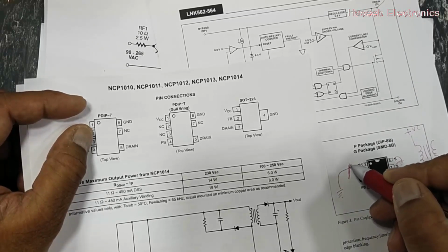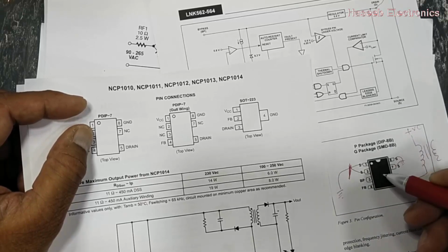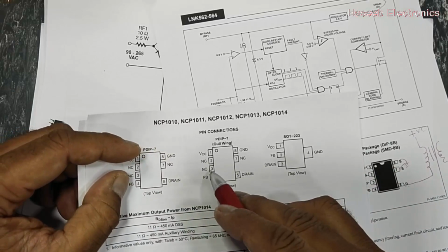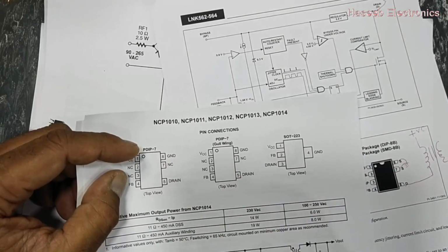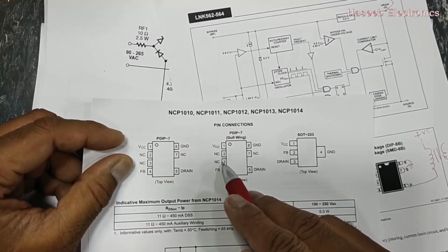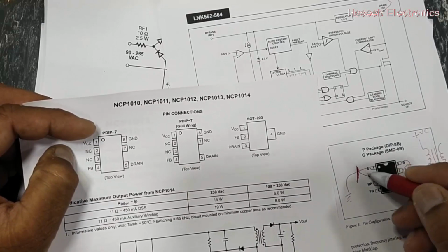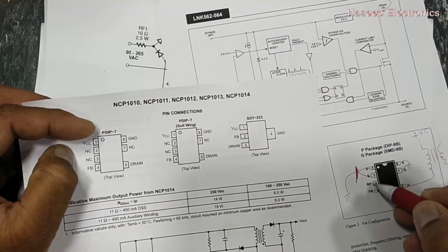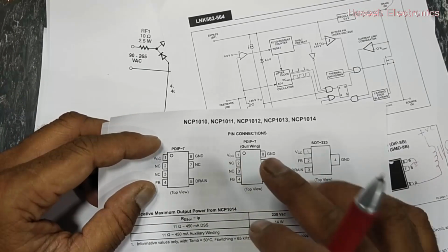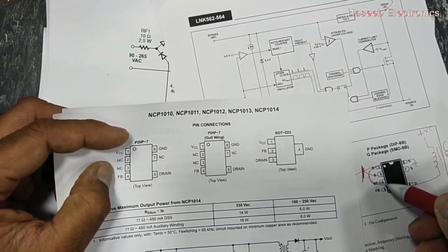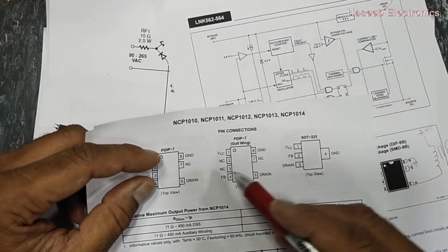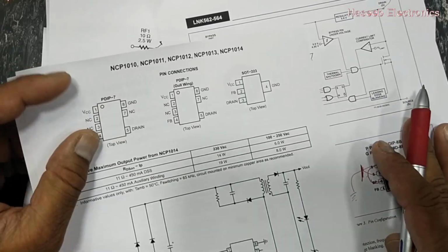We have to disconnect the track, and then we have to connect this pin number 3 to the VCC pin, because in this format pin 3 is not connected. We have to disconnect the track from the PCB, and we have to make a jumper wire for this IC. When we make the jumper, in that case the bypass pin will be considered as the VCC pin. So this IC will work in this place.